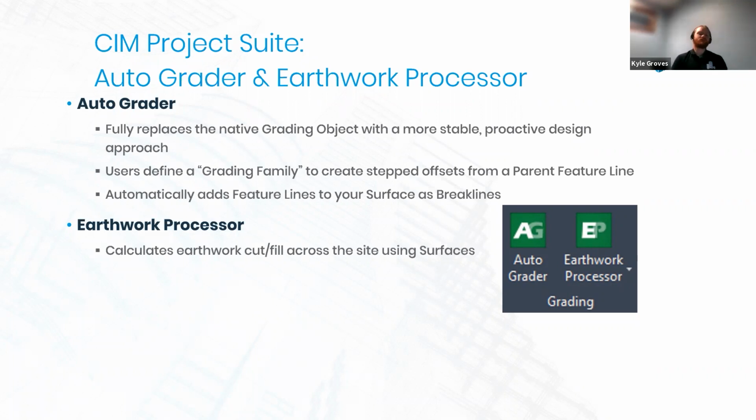Next up, let's talk about Earthwork Processor and get a quick preview on that. So Earthwork Processor's job is to calculate your earthwork cut and fill across your site, and it's going to be using your proposed surface and your existing surface. There are other surfaces that we need for this workflow. Check out my webinar from April for a detailed workflow on how to use Earthwork Processor and also how to come up with a decent out-of-the-box method. My coworker Brian Tanner also had a pretty good one around that time. He used slightly different methodology than me for the out-of-the-box stuff, but both are great if you're trying to learn more about how to do your site balance calcs inside Civil 3D.